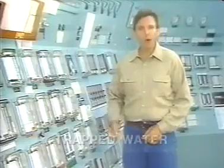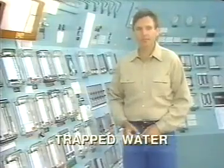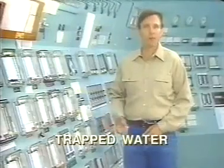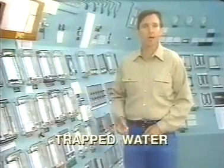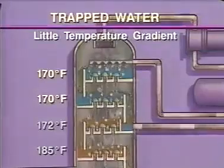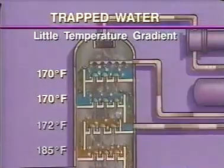Abnormal operations can also be caused by water that inadvertently enters the system. The water may come in with the feed or accidentally through a pump line and gets trapped in an area of the tower where the temperature is below the boiling point of water. Most hydrocarbon streams are lighter than water, so they float on top of it.